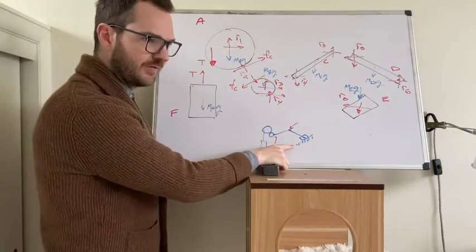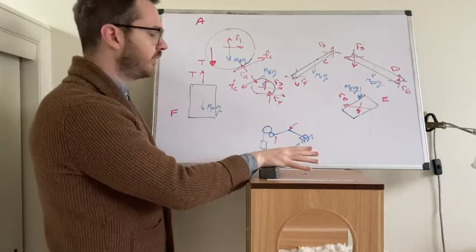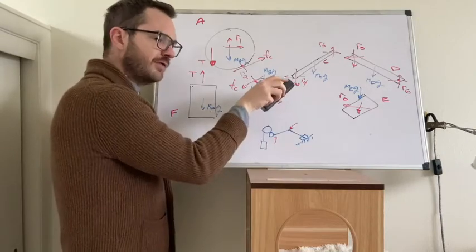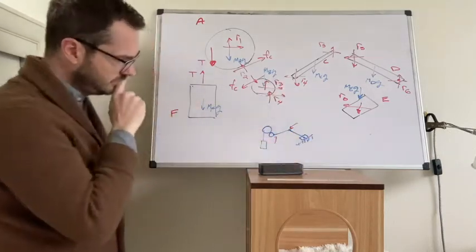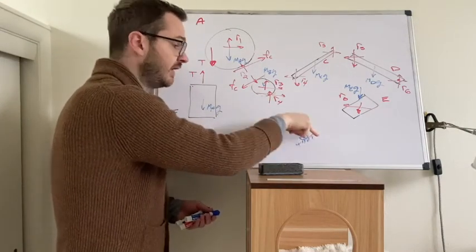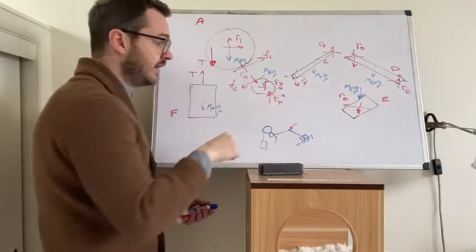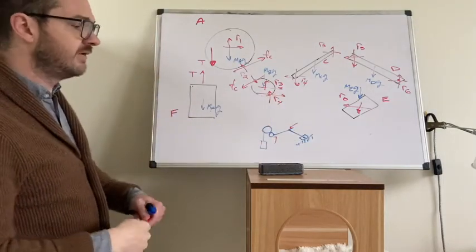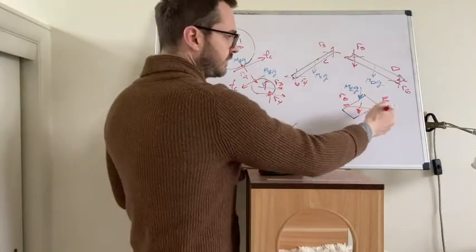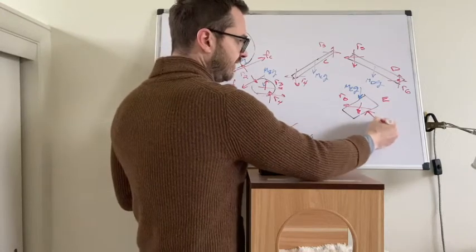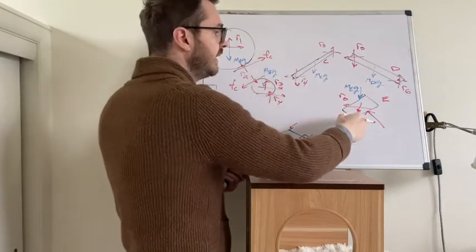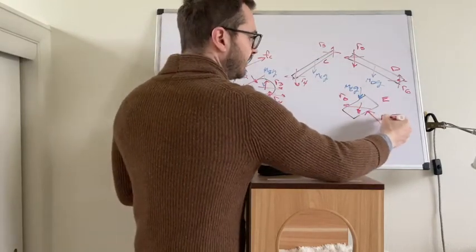What else is going on with block E? Well, block E is on a surface, and there are constraints associated with that surface. Even though it's at an angle, it's at a slope, the block cannot move through that surface. So it's prevented from translating in that direction. So that's the constraint. The constraint is it can't move this way. And because there is a constraint, there has to be some reaction force enforcing the constraint. So here's body E. The constraint is that it cannot move into the surface, so there has to be some reaction force pushing it back. R6, so this is R7.